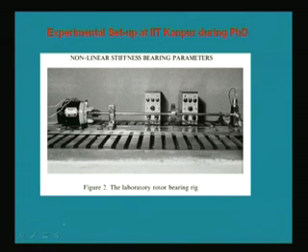This is another setup. You can see there is a solid foundation. Generally we need that when we conduct the experiment, so that whatever vibration we have here should not go to the other instruments nearby. And here you can see there is a motor which is rotating a shaft mounted on two bearings, and this bearing has a measurement accelerometer.